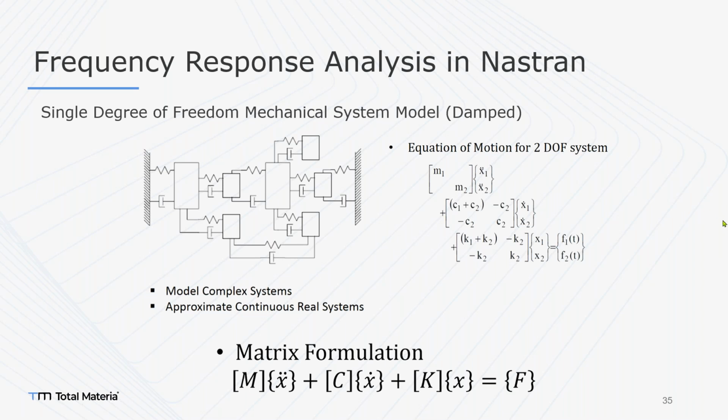So we need to consider which areas should be treated as damped or undamped, and what the total matrix formulation of the system should be. Should we include everything in our product, or, for example, for the body in white in the automotive industry, we don't want to add everything in that product. We may include just some elements and parts that need to be considered.